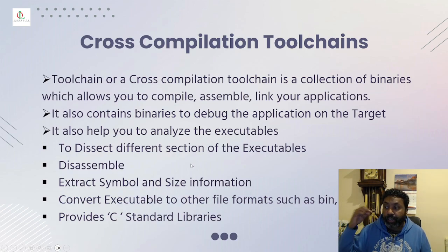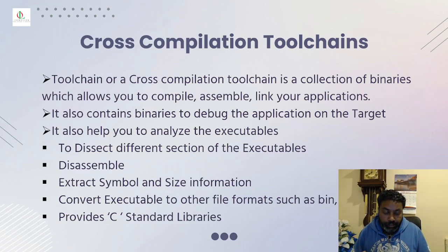From when you compile the program, it will help you understand what the sections are. Disassemble converts from C language to assembly language. The toolchain will also help you extract symbol and size information, for example the memory allocations, the flash memory and the RAM sizes. So that's what the analysis will do.